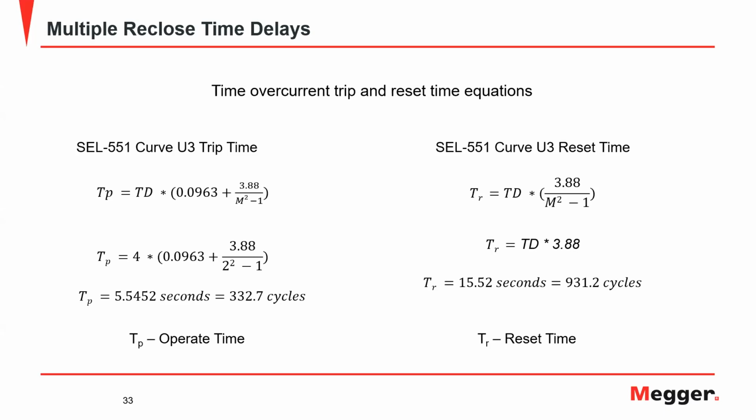In some cases, what you do is you sense voltage on one side, let's say on the load side, and sense voltage on the line in order to verify that there will be proper synchronization when you're doing the reclose, just in case that you have some sort of feedback from the other side.